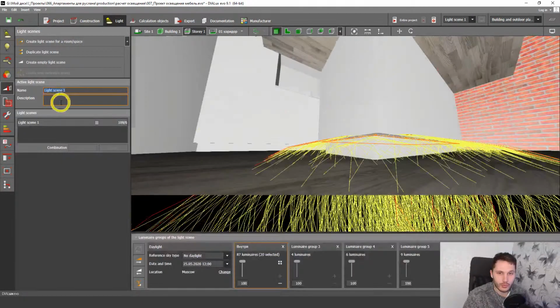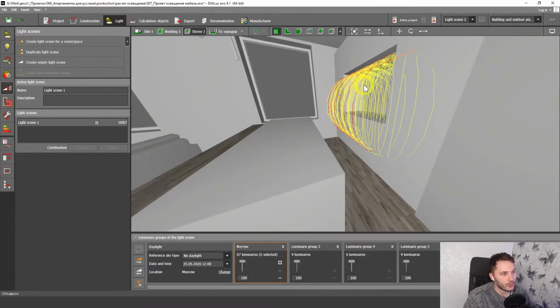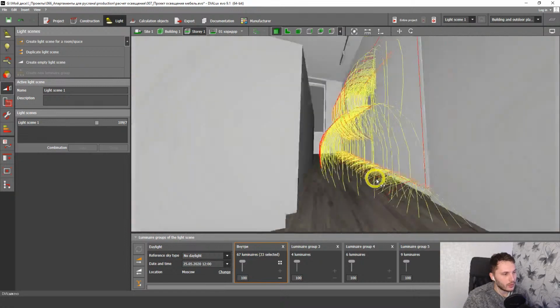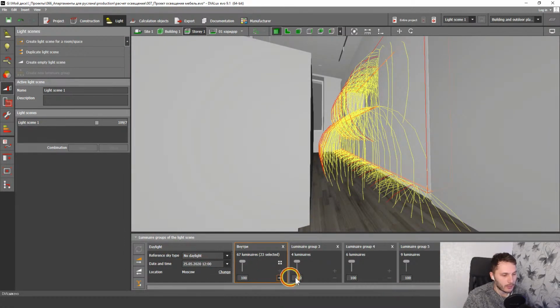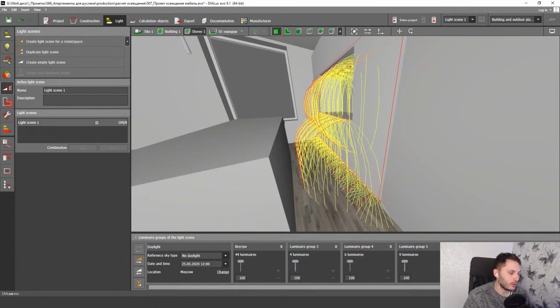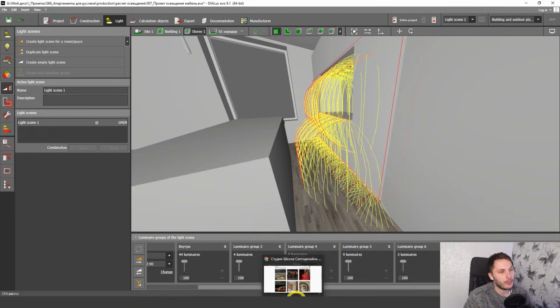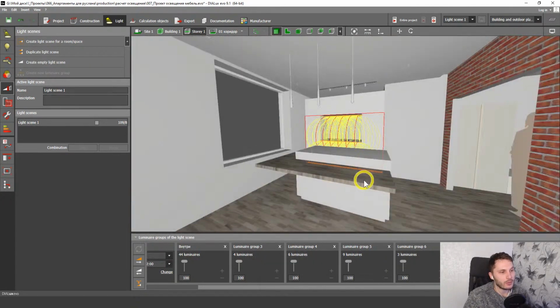I'm going to the groups in lights, subtracting from our entire group, and creating a new luminaire group with these 20 luminaires. Then I'm going to subtract from this group and create another group. I'm doing this because I want to dim something, and when I manage the control system, I'm going to use these dimming levels.